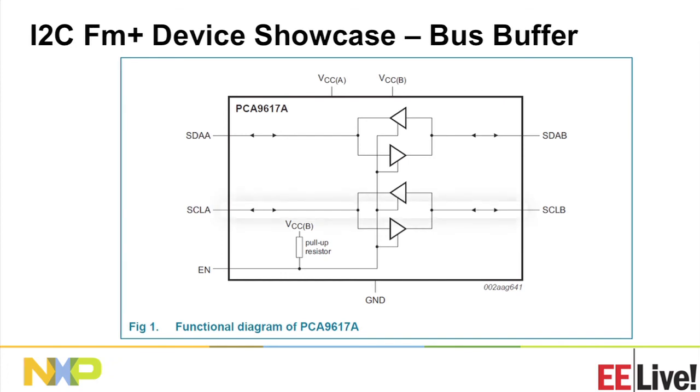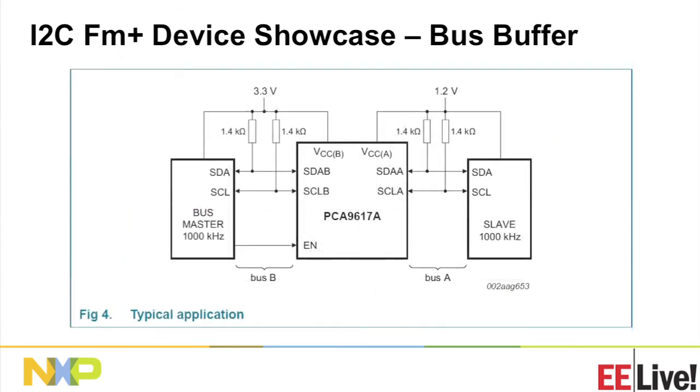Because if a signal is passed through this path, it is also reflected in this path, and you end up with a race condition where they lock up. Both buffers will turn on. The only way to turn them off is to cycle the power. So we design them in a way that when you're going in this direction, the signal coming out here is okay for the load, but is ignored by the device going in the other direction. And that's the reason for the little step in the logic 0. We call it bus buffer offset.